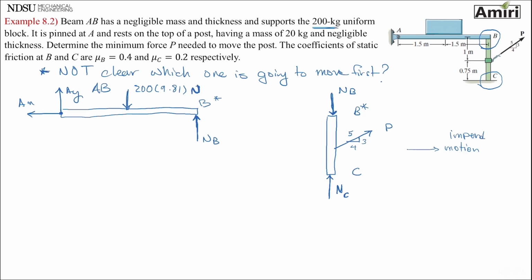So for C, the friction is going to be opposite of that, and it's the same beam, so friction for this one is also going to be opposite of movement. Now that's a little bit easier. Now I can go back to AB and put opposite forces of friction on there. So remember, exactly like frames, when you put these 2 points back together, the forces should cancel each other out.